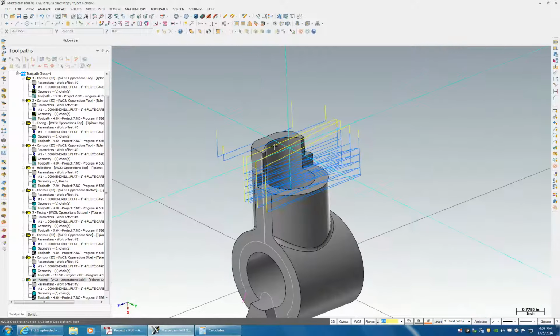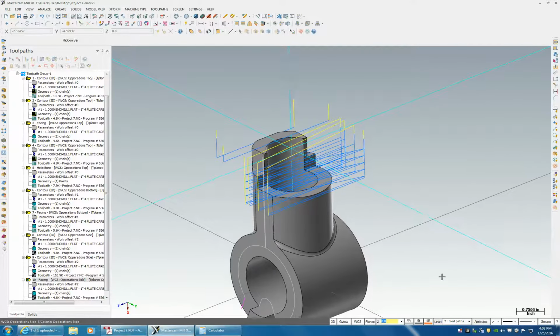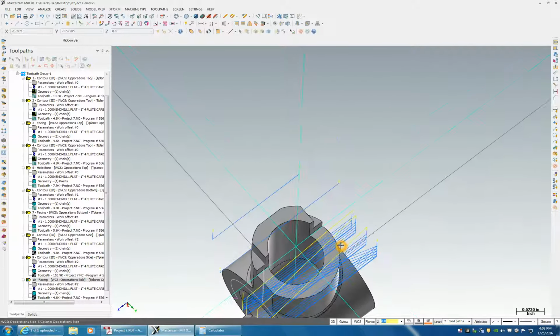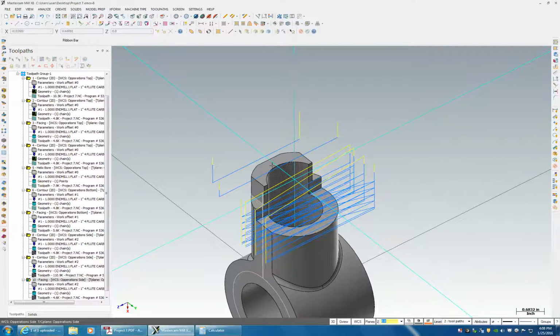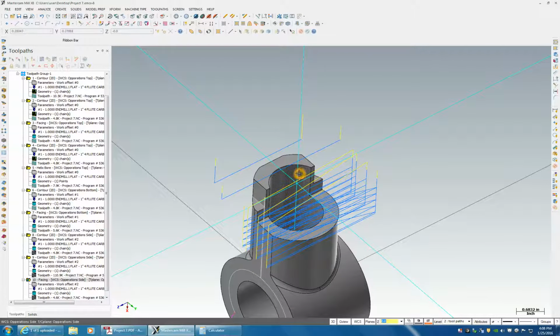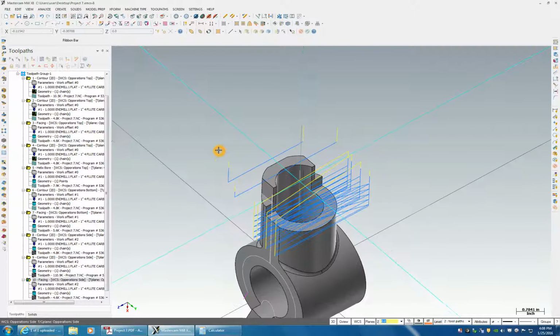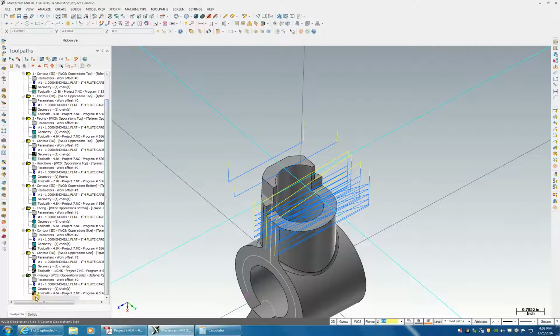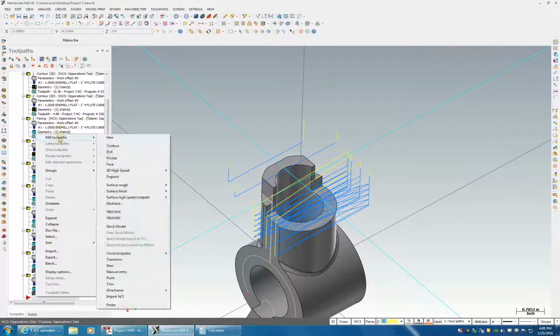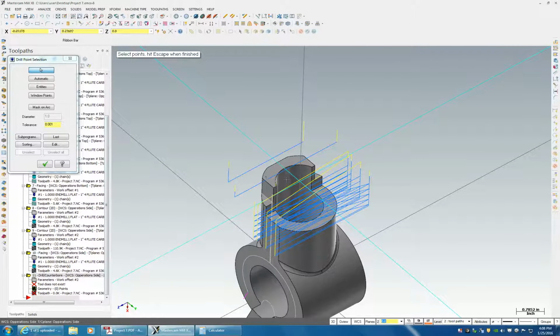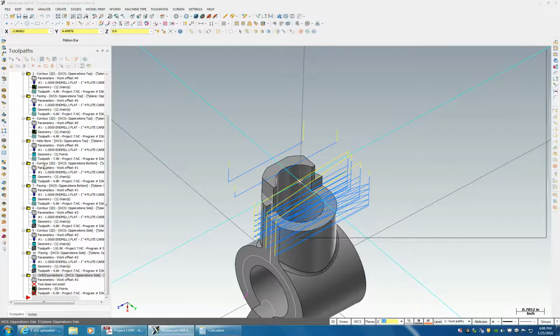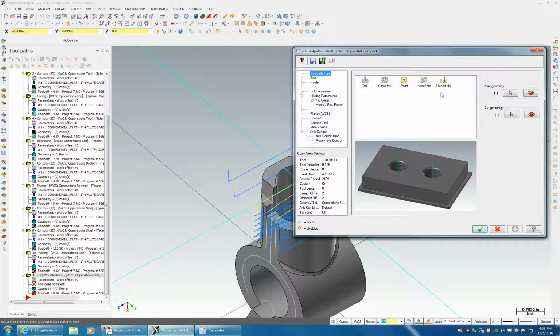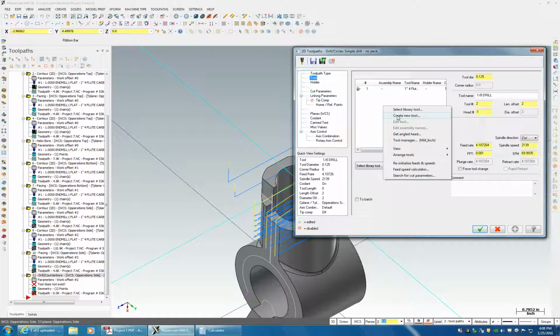Okay, so one last thing to do. We're going to use that helical interpolation again. Actually, let's set up a brand new tool. We're going to bore that. Use a boring head. Mill toolpath drill, and we're going to select the center of that arc. Prove that. I'll leave it at drill. We're going to tool, create new tool.